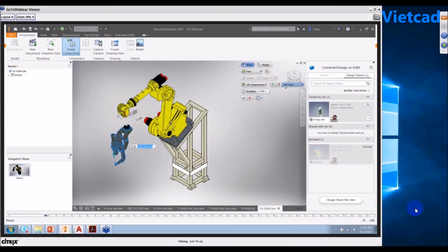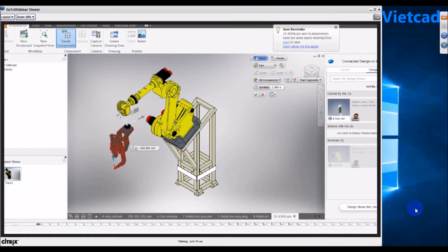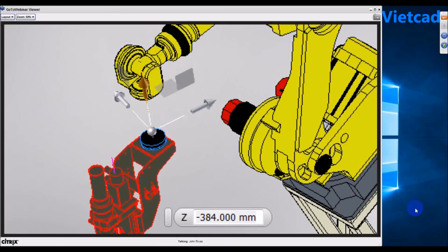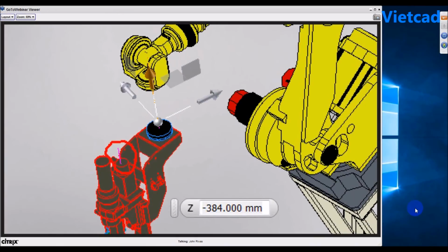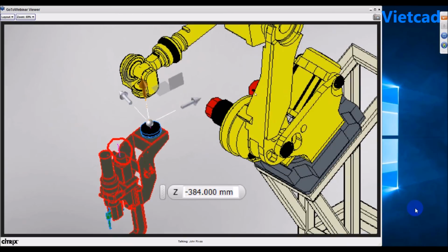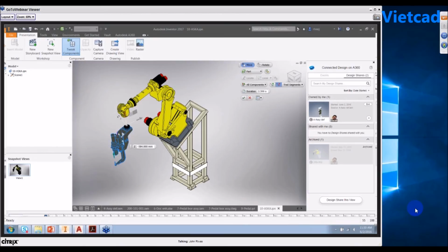There's an option here as well, wherein you want to create a full trail or you want to create trail segments. Meaning this one is actually the lines. Maybe I'll just zoom in closely here so that you can see. So these trail segments are those purple lines over here. This can be used for your drawings, and some of them, there are things that you don't like. You can just simply delete those away. By selecting delete existing trails, hover your mouse on that sketch and then delete.